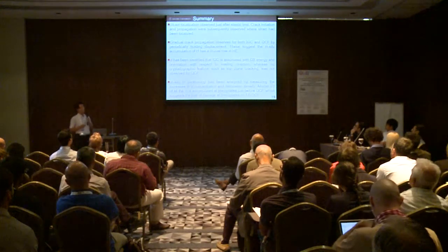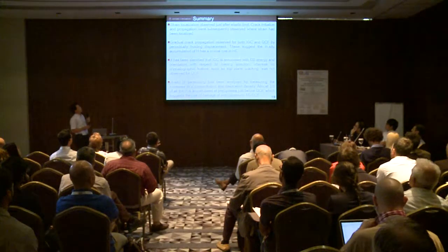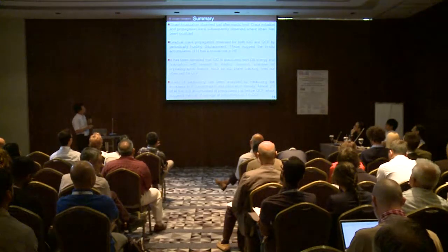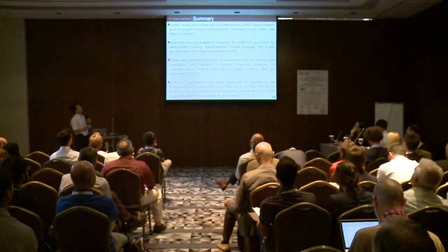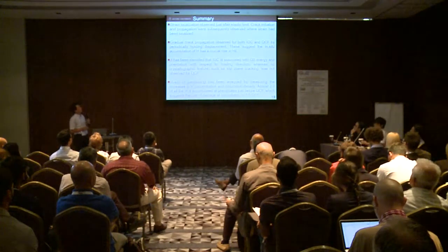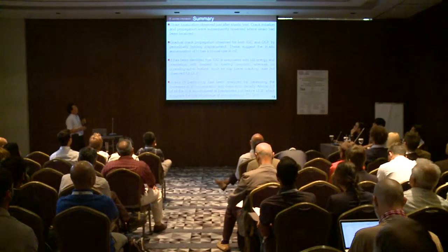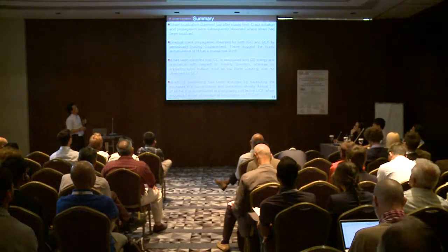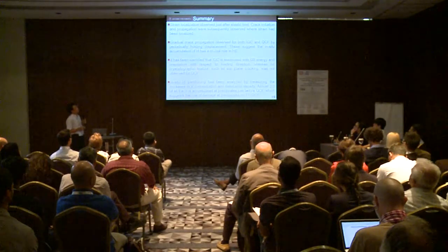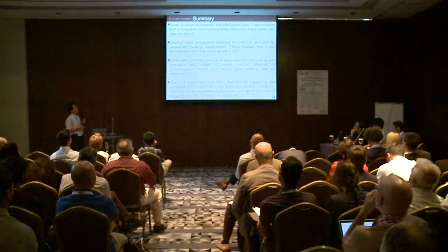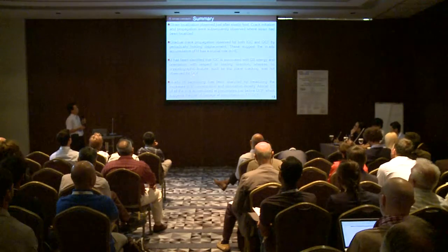concept of brittle fracture. And if we hold the applied displacement of a specimen for a holding time, then we observe hydrogen embrittlement. And hydrogen embrittlement is associated with grain boundary energy in the case of intergranular cracking, but we don't know much about quasi-cleavage fracture at all at this moment.